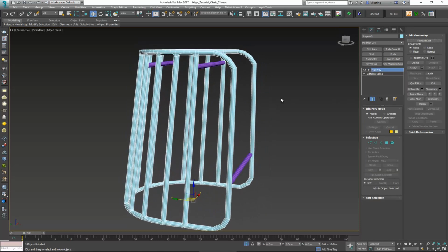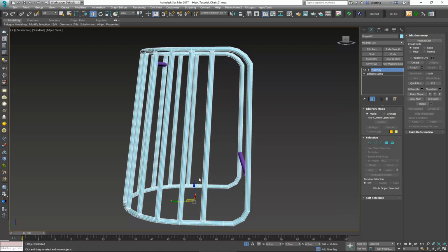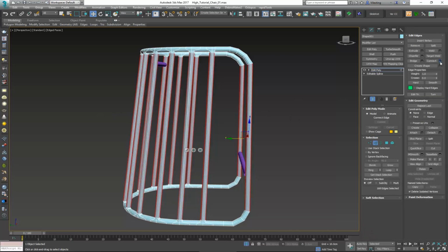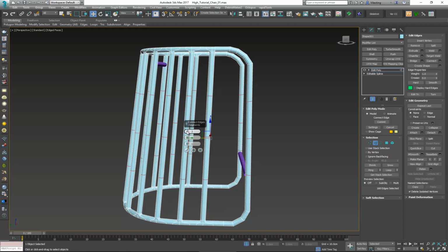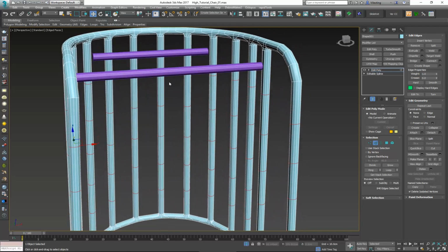And also, here's another thing you should always keep an eye out for. When you have a model that has elongated polygons like this, what you want to do is generally go in and add in some connections. This is going to break up those very, very long polygons. That's going to actually help with stretching. So like this, that's fine.